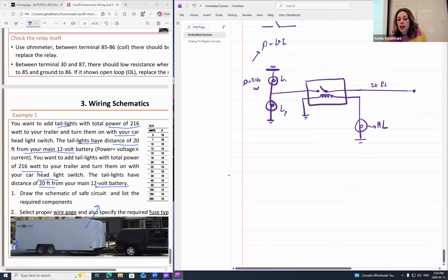And this is the symbol. It's like a tile, right? And right after that, I can include this one to be my battery. So this is my fuse, right? And this is my battery. Therefore, I have to include it right after the battery and before the relay, because if the fuse is sensing something which is not normal, then the relay causes the connection to be disconnected. And then I'm going to protect my loads.